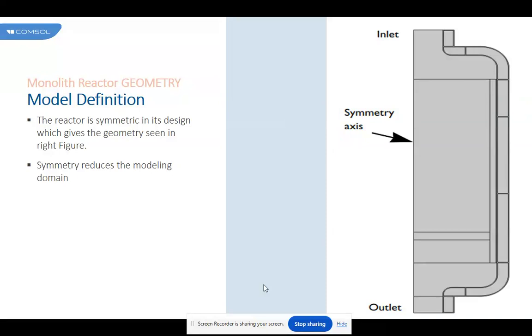Different models are available for calculation of thermal and transport properties. The viscosity of the system is calculated based on the Brokaw model. The thermal conductivity and diffusivity are calculated from kinetic theory and Fuller-Schettler-Giddings respectively. In this model, to simplify the problem, nitrogen is modeled as a solvent. This means that the gas properties are not composition dependent.